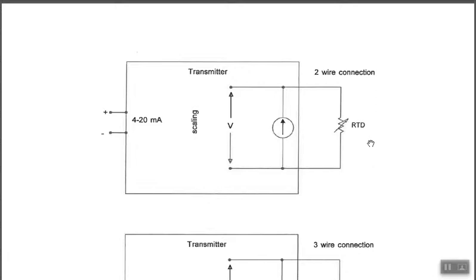That way it's mostly immune to corrosion and things like that. Typically, maybe 100 ohm platinum wire might be one you'd run into, but that's what you're going to have sitting right here. Now the resistance is going to vary with temperature, just as metal does.